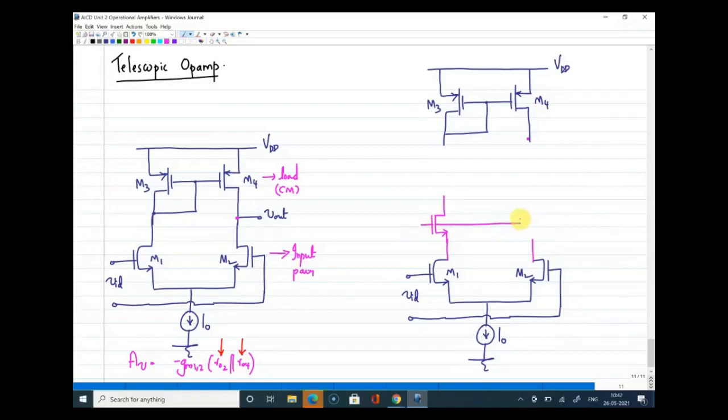If it is folded cascoding, I will use a different device. So these are the two devices I have added here, basically to cascode, or to increase the output impedance of, M1 and M2. Previously the output was taken with, okay, we'll talk about output a little later. And this needs to be biased, so I am just marking it to a bias point.